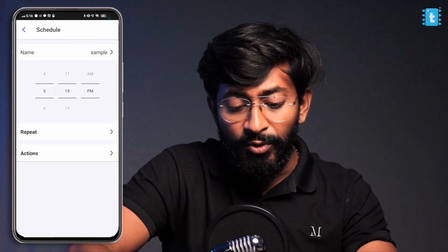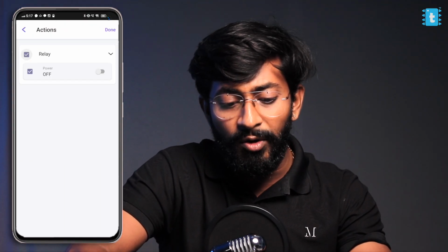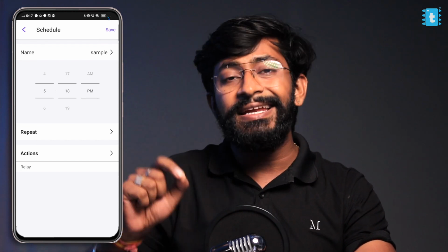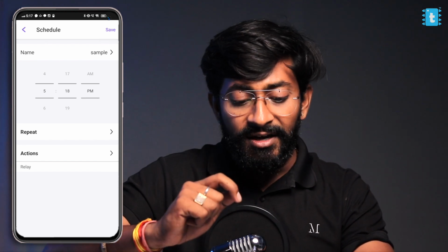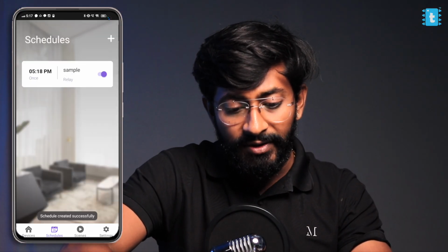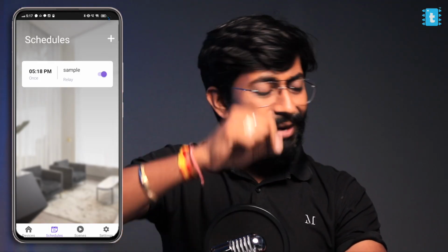Do we want to repeat it or not? We don't want to repeat it. The action will be, I want to turn on the relay. That will be the action. So at 5:18 p.m. the relay will get turned on. That's the automation we have programmed here. And then let's just click on the save button. Okay, so it's turned on right now. It's 5:17, so after 1 minute the bulb should get turned on.